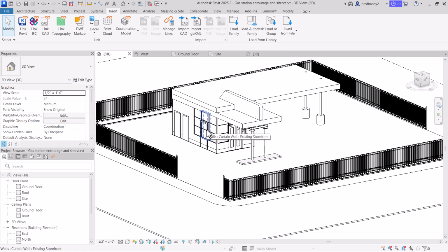The reason is when you import it this way, it just sits in the model. It's a little harder to update the model. In our case, we may want to repaint this model. The only way we can change or divide up the paint colors is in SketchUp. We can modify the paint colors that are on there now, change them in Lumion, but if we want to divide them or change them in some way that involves changing the geometry, we need that SketchUp file, in which case we can link CAD.